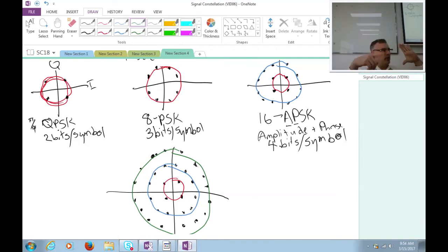And if I have some pilot symbols, I can maybe transmit some first symbols on the outer ring and some symbols on the inner ring, kind of in a predetermined pattern, so that I can compare that and say, well, look, it looks like there's some nonlinearities here. Maybe I just need to redraw my decision boundary for this constellation, taking into account that I've compressed it a little. So first I determine, just by looking at the power of the signal, which is very easy to do and to measure in hardware, which ring this symbol is on, and then once you've determined the ring, you pick the phase and try to estimate the phase and figure out what the symbol is from there.